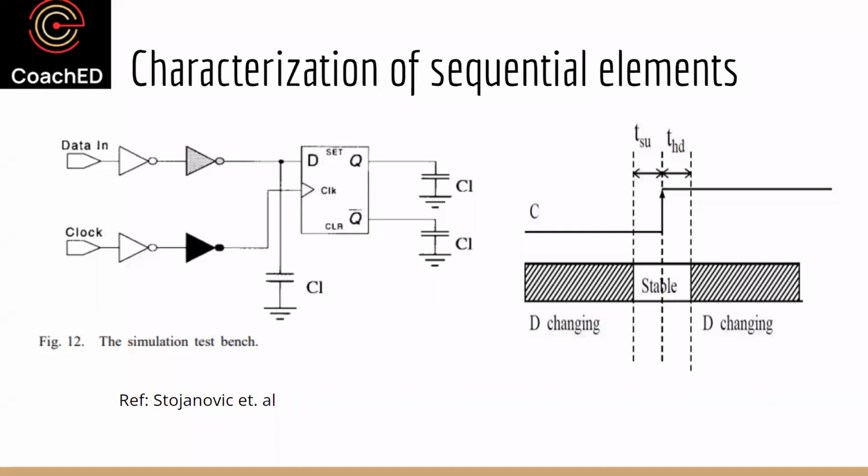This means that as the gate becomes bigger, there will be proportionally higher diffusion capacitance, which means higher parasitic capacitance. So the self-loading will be higher. But because its drive increases, it compensates for it.